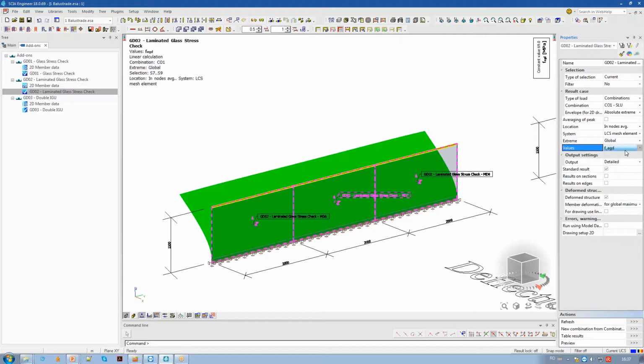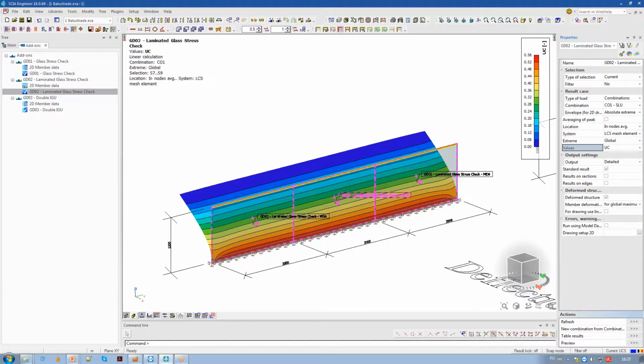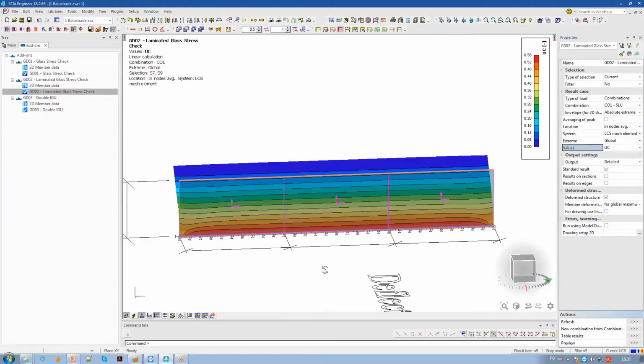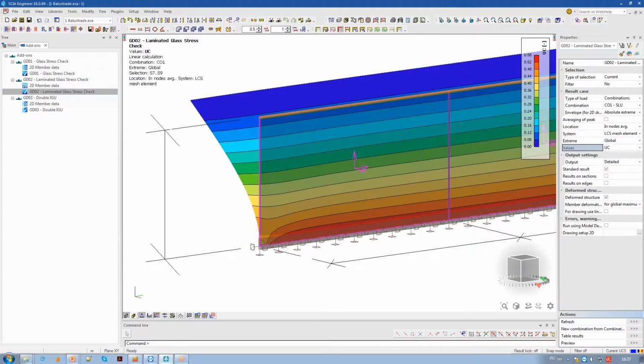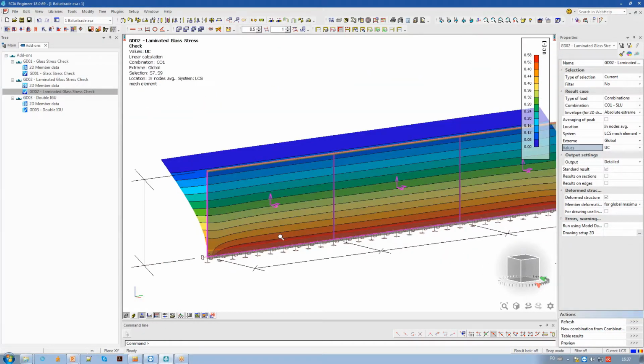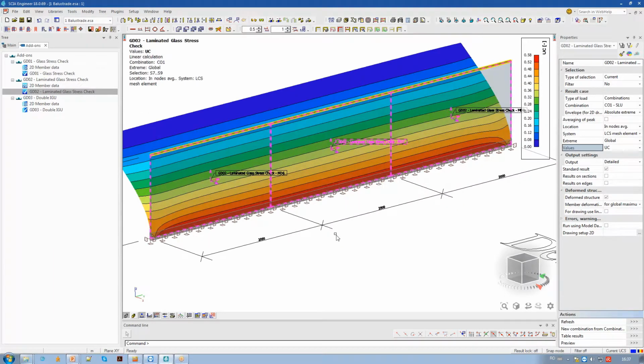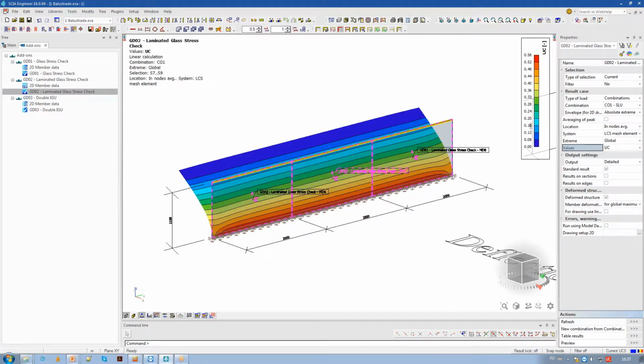And then I can go with unity check, because it will show me the ratio between the force and the capacity. So as long as I am under 1, I am safe. If I'm under 0.5, it's not that economical. So we see here the distribution, the influencing of the corners, and this is the unity check shown graphically. And we can send this to an engineering report, even as 3D PDF.